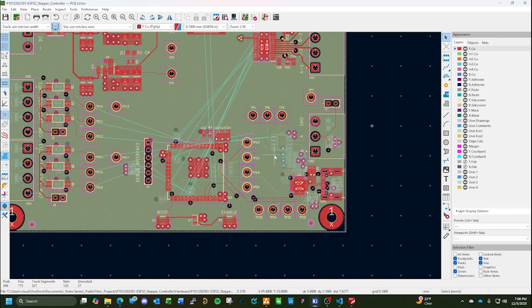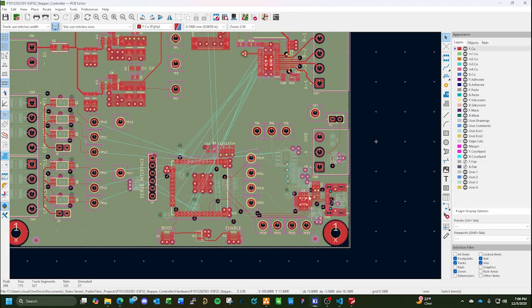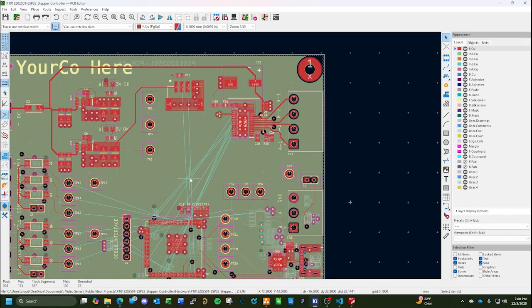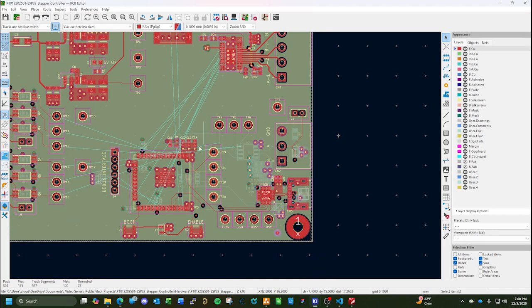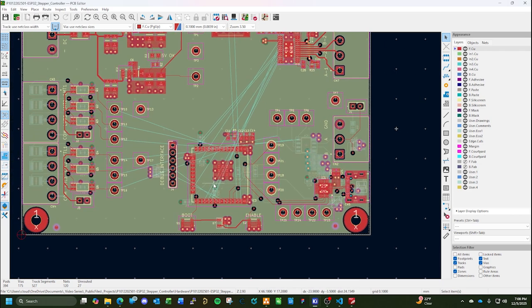So that plumbs in quite a few of the supporting components and systems. Now the really complicated layout's going to come in to basically bring all the inputs in, tie them to the ESP32, the drive out, the control outputs and inputs to the stepper controller and the RS-485 interface. Cool thing is we got the UART programming interface already plumbed in. So it's just going to be spaghetti heaven. That's why we've got a 6-layer board. So we have a total of 4 signal layers to handle this routing on.